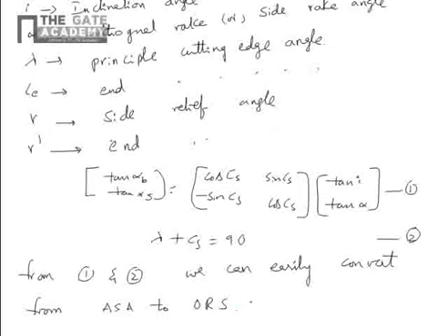If they give lambda, then you can substitute the lambda value and get CS, then substitute CS, inclination and alpha. You will get the values of back rake angle and side rake angle. This is one you should remember, the formula. There is no other way to remember this. That's about orthogonal angles, ASA system and geometry of the tools. Next one is orthogonal cutting.